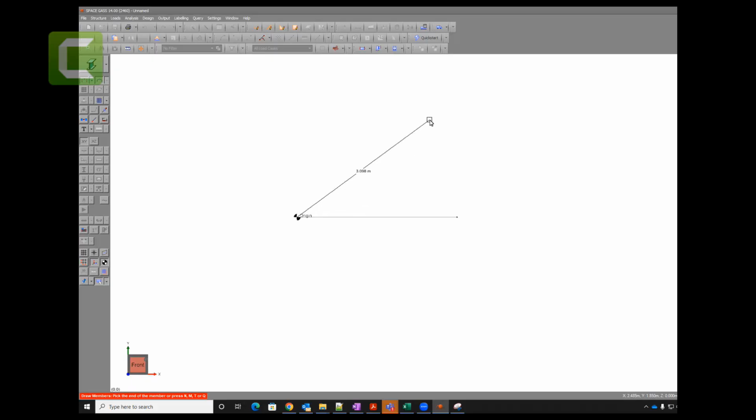And then on your keyboard, we can put the coordinate. I think we cannot put the coordinate 3. Yep, you can put it 3, 4, right? Because X, Y, and Z is 0, so you don't need to put it there. And hit OK. So there you go.